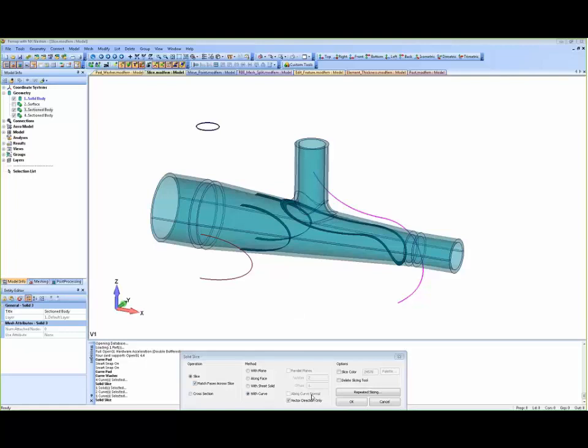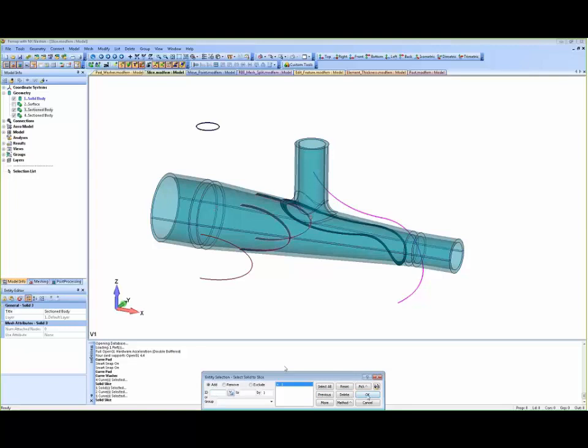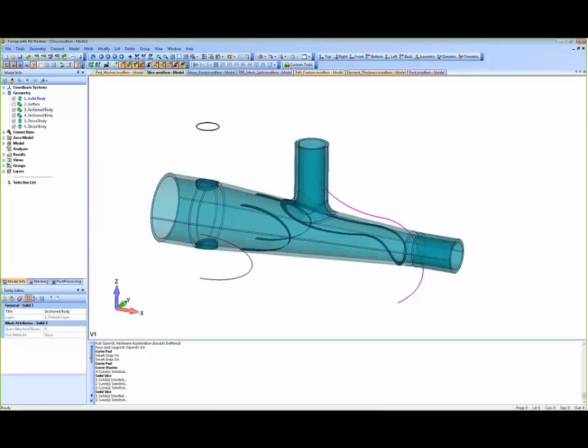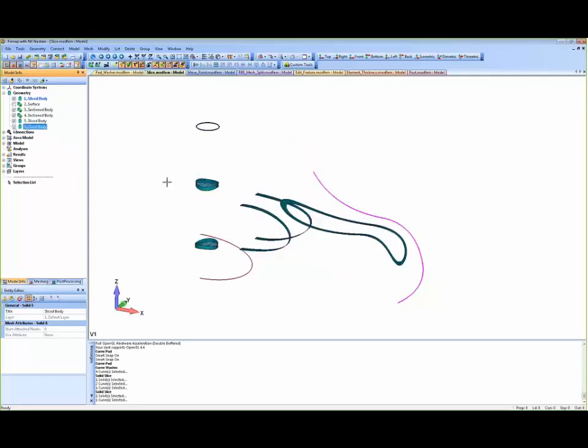So here, I'm going to do the with curve option again, and I'm going to hit OK. I want to slice that guy. Select curve, I'm going to do that circle up there. And in this case, I'm going to do the -1 vector. And there we go. It created the 2 separate solids right there. And now those faces match. So again, in meshing, it'll put coincident nodes along those faces, so you can not worry about a connection if that's how you want to connect your model.